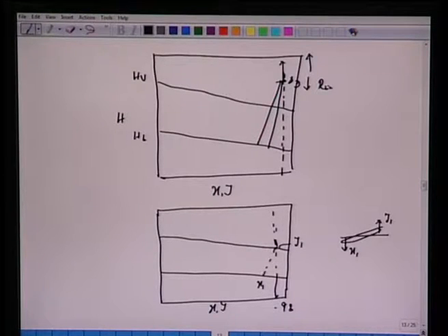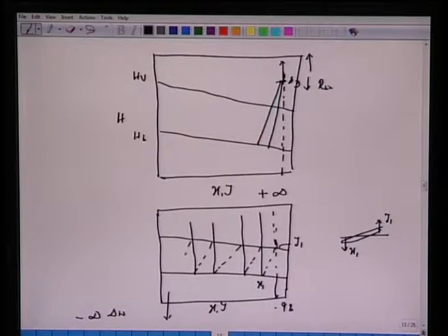Once we have X1, we draw the vertical line. This is the operating line because this comes from plus infinity. I realize that if this point goes up, this del W point will also go down to minus infinity. So essentially we have all these vertical lines going upward like this, till we have reached, or at least crossed, this XW, bottom product, which was 0.0057.